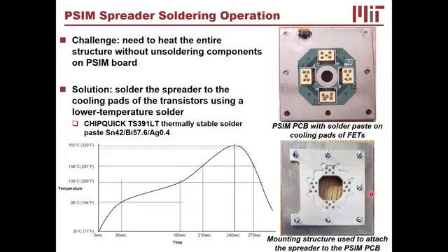Now I've got this heat spreader, which has really low thermal resistance, right? So I've gone from my chip directly to the heat spreader. And by the way, I said this thermal pad on the device is actually connected to source in this particular device, and source is ground in the particular circuit. So I can basically make this whole heat spreader and the whole thing electrical ground. That's kind of nice.